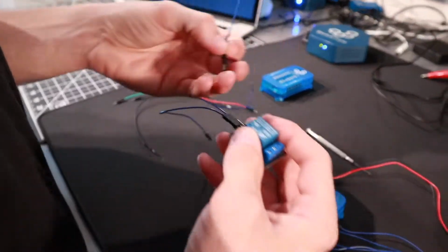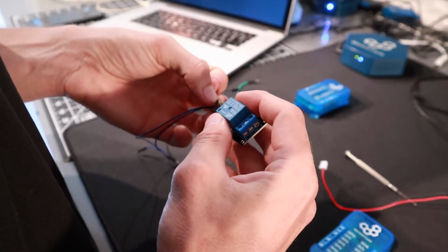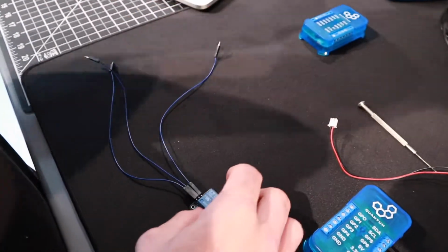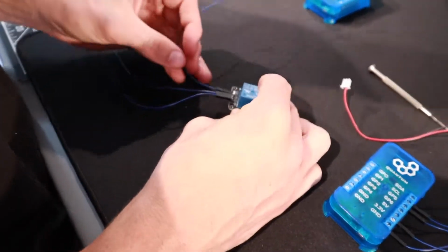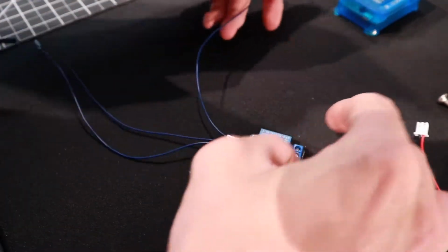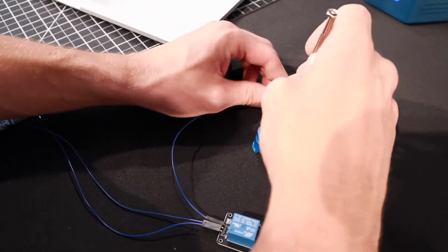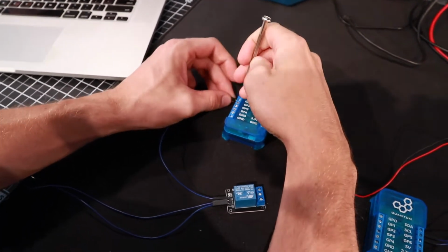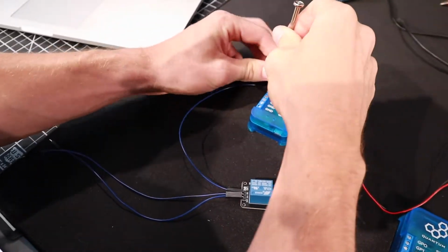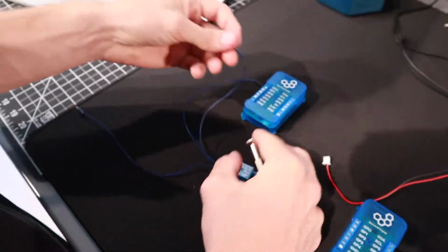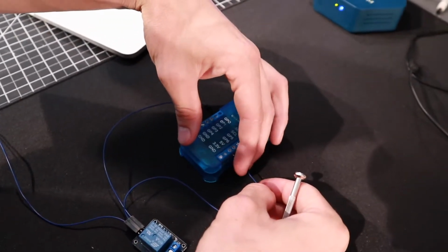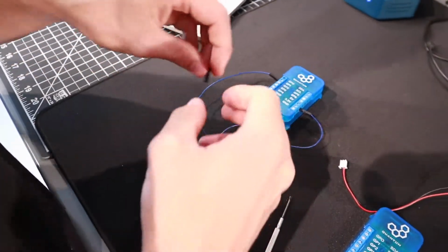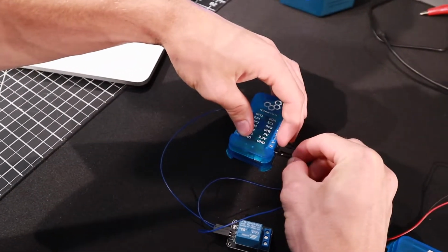So now we're connecting the 3 male-female jumper wires remaining to the low voltage grouping on the relay. From the signal pin on the relay, connect that to the GP0 port on the other client. And that's what we configure later on in the firmware, right? Yes, exactly. Then we'll connect the VCC pin to the 5-volt port on the client, and the ground pin to the ground port on the client.